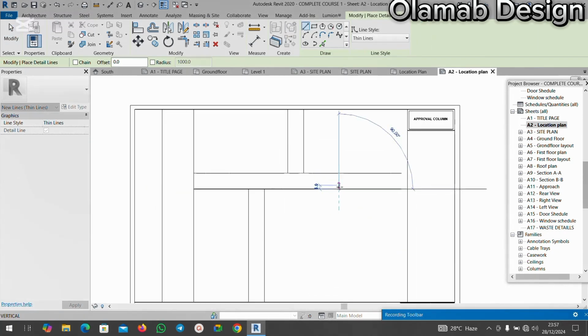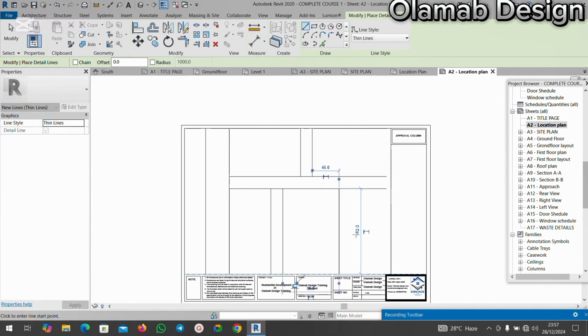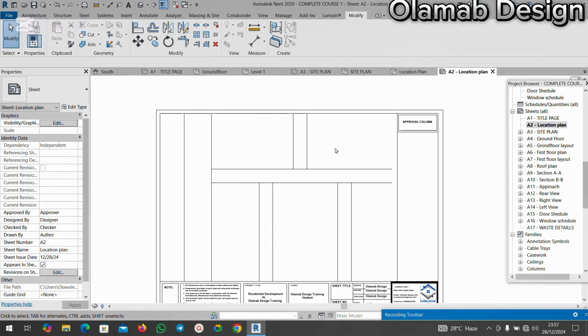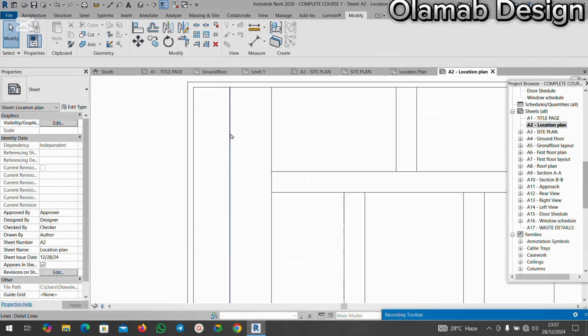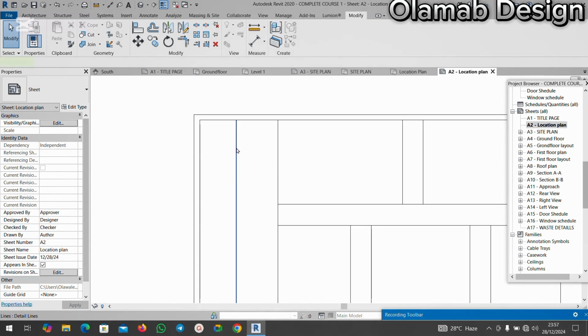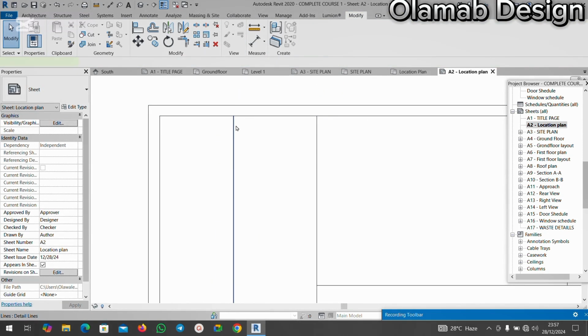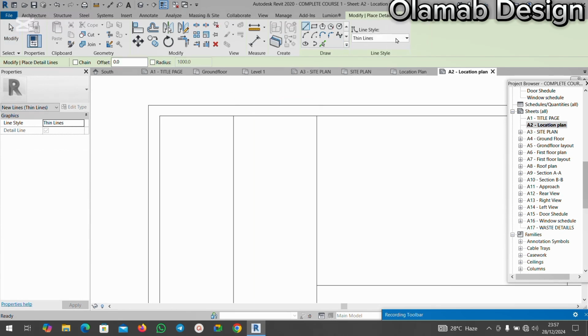After hitting on the line, then you hit on this and draw it this way. Then you offset this also, offset by 20. You draw this way. Then right here, I will also locate the center of this. I can hit on this line, hit on create similar. Then I will draw this way. I'm still going to delete that, hit on line, create similar.